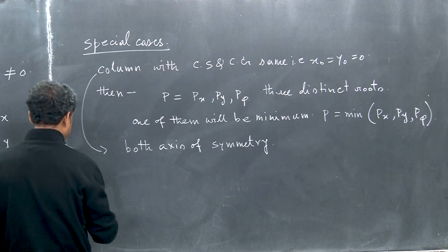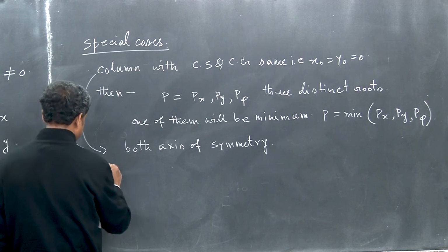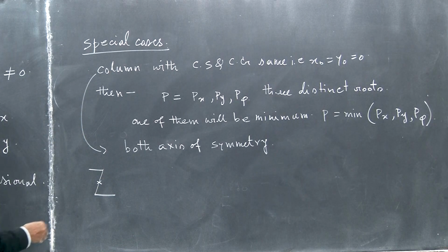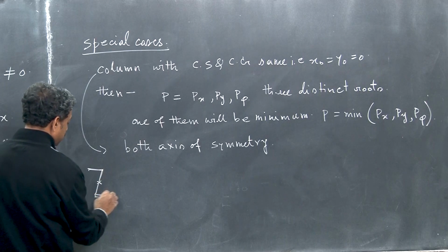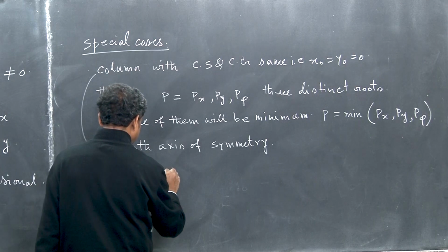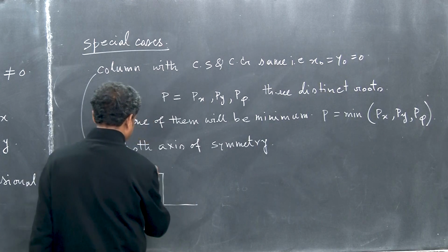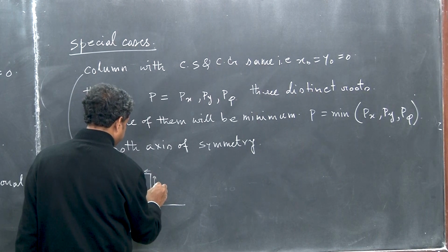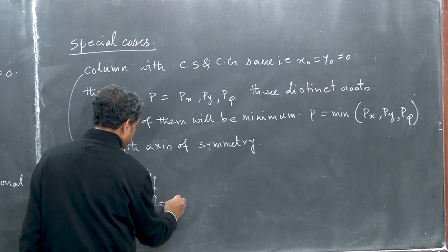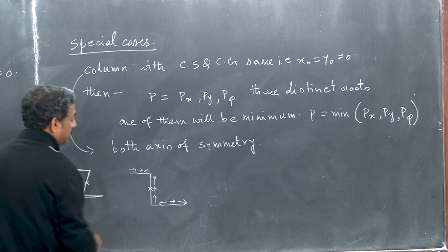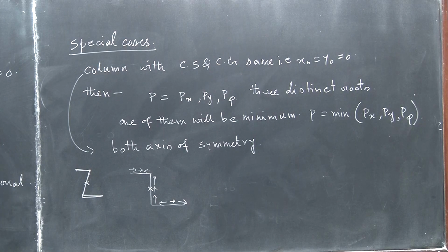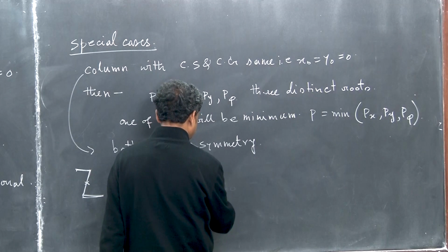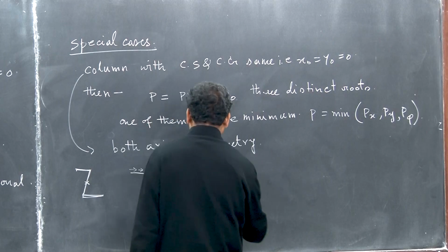So for that I section, and also for the Z section, the shear center and CG are the same, okay. So, what is the shear flow diagram for the Z section? The shear flow diagram you will see for the Z section, whatever comes from here will be different, okay. And then from here, CG and this are the same, okay, and then it will have torsion, and then the I sections all have both axes of symmetry, right, I section.